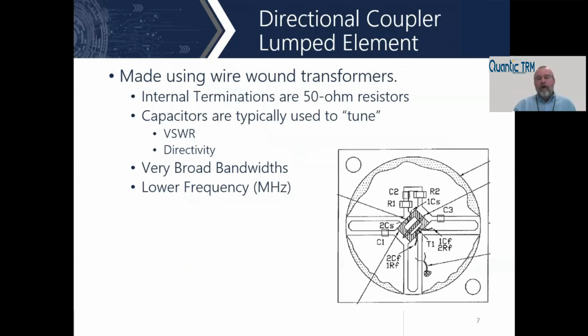Sure. Now, going away from the generic kind of what is a coupler, we're now getting into how we actually make these, and by making these this way, we can accentuate some of the properties of the technology going forward. All directional couplers work off of the fact that if you have a varying electromagnetic field, and a wire or a transmission line is sitting in close proximity to the line that the energy is going down, it will induce a current in the opposite direction in that wire that is in proximity to it.